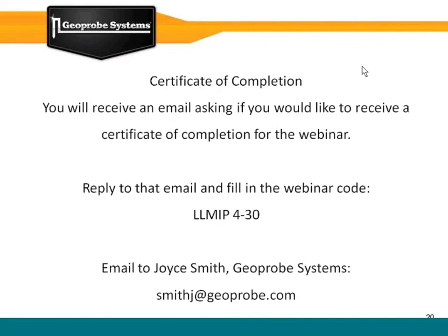If you're normally waiting 45 seconds to a minute, it might be a minute and a half. So you might have like 1.5 times the length of time that it would take to do a log. So if it's a 60-minute log, it might be 90 minutes. And that's actually on the logging side going down. Your movement between holes or pulling the rods is all the same time. On some of the logs we did, we figured half a minute a foot more. So on a 60-foot hole, we were looking at an added half hour over standard MIP.